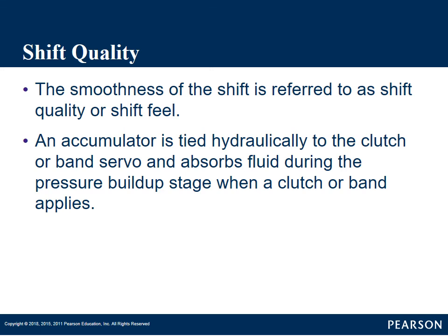Now we're going to talk a little bit about shift quality. This is important when we get into diagnosing transmissions. Basically, how smooth the transmission shift is referred to as shift quality or shift feel. When we were talking about accumulators, we were talking about slide bumps where the accumulator slowly engages and then locks real tight right at the end. Or you can get a transmission that has a real short shift and harsh shift, or a long drawn out shift over a long period of time.